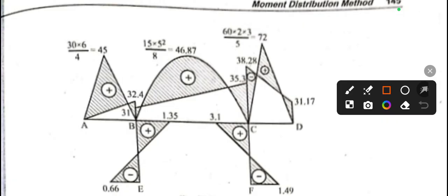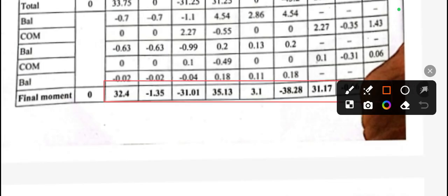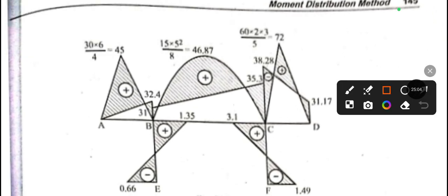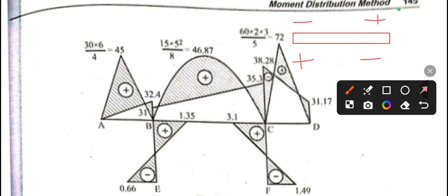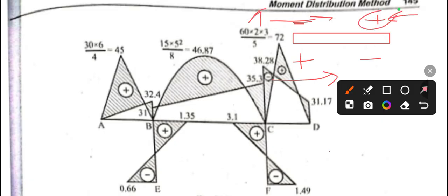In the bending moment diagram, it is very important to first plot all these given values. Just put all the values, and while putting values you have to remember and always follow this sign convention: minus, plus, plus and minus. When you move from left to right, we take the minus sign as the upper part of the beam, and from right to left we take the positive value as the upper part of the beam. From left to right, a positive value is below the beam, and from right to left, the negative value will be below the beam.